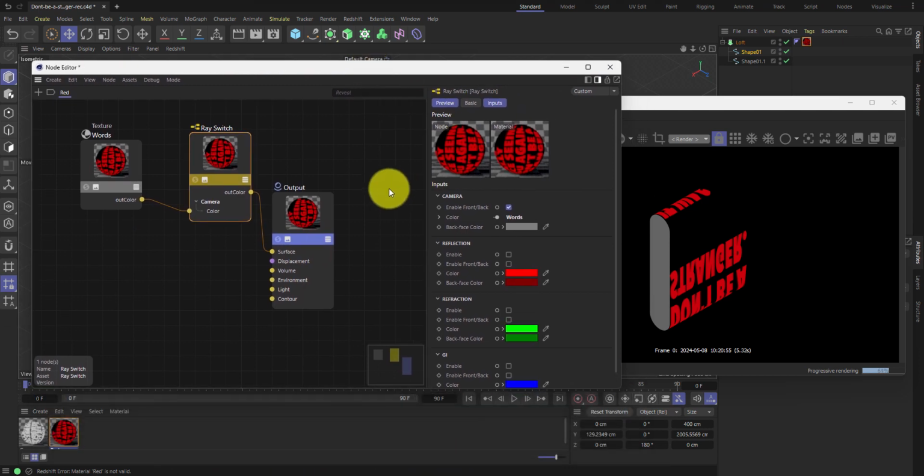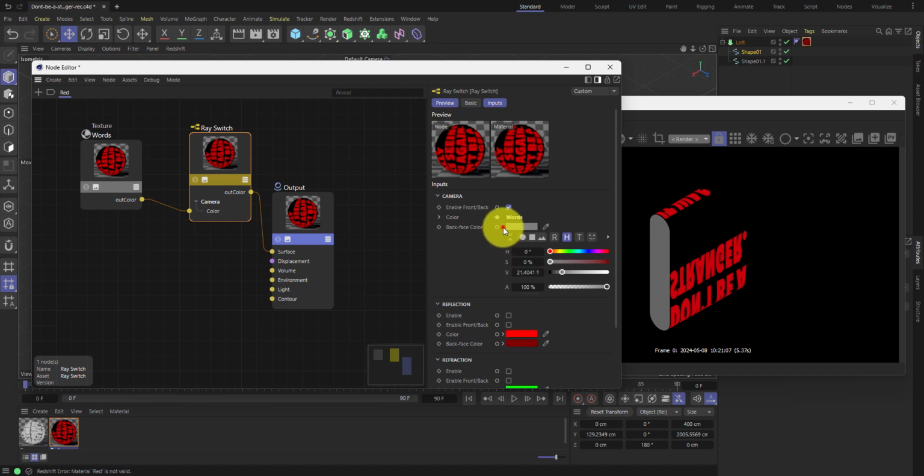Okay. So now what we want to do is make that transparent. We don't actually want this gray shape in here, obviously. Now you'd think it would be simple. You'd think you could just go to this back face color, which is the face inside this shape here, that it's made gray, that gray there. And if you go here, you can change the color of this, make it a bit brighter if you want. Obviously you don't want that. You want that to be transparent. And you'd think that if you just drag this alpha to 0, it would fix it. Unfortunately, it doesn't work that way.